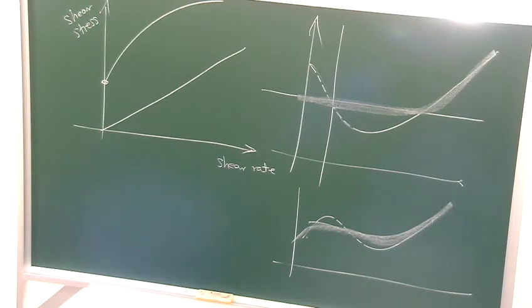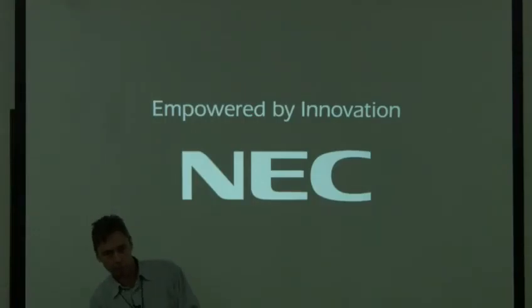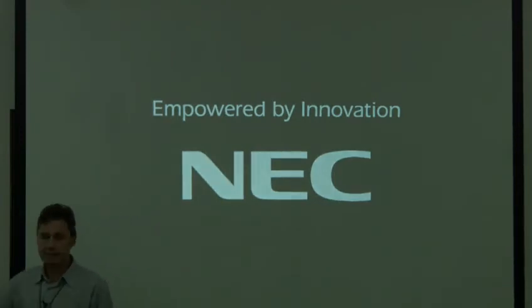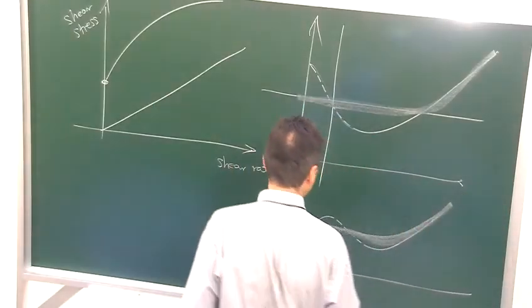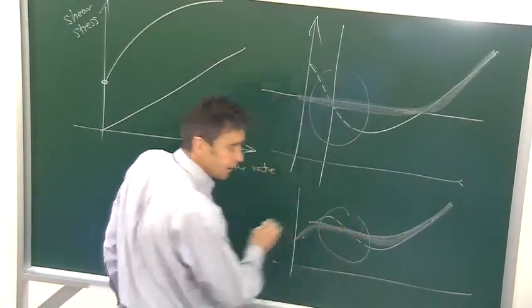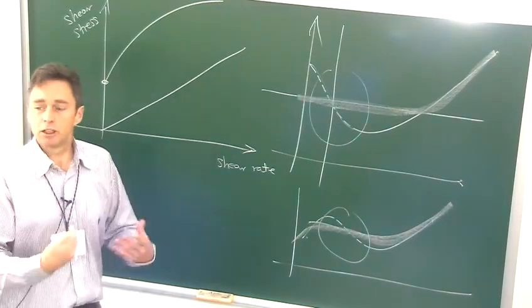So people actually try to interpret this a little bit more by going to the rheometer. So the rheometer is normally quite small. It's this $100,000 device that you really don't want to touch. However, people decide that, well, we really need to see what's going on inside the sample, so you get rid of the bottom, you put a transparent plate in there, then you seed the fluid with particles and you do PIV through the bottom. And when you do that, you can actually build up what the actual rotation rate is inside the sample. And so what you find out in these situations is that there is shear banding.